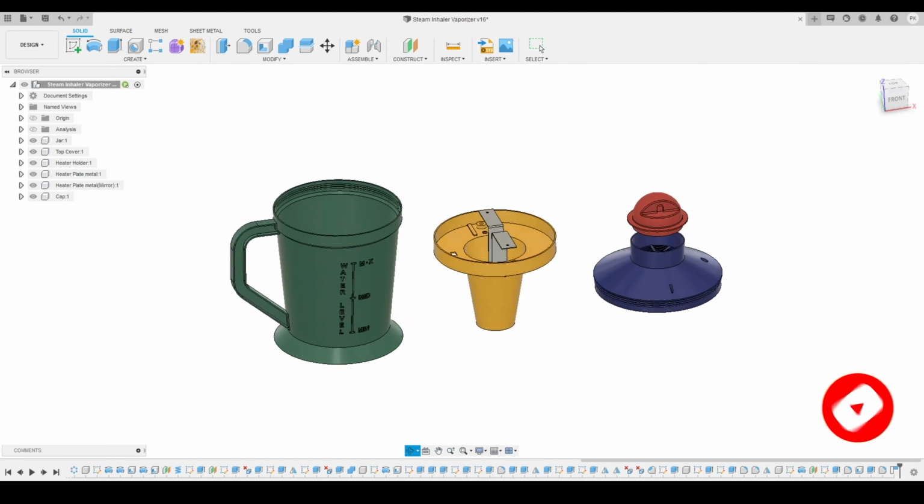Here you can see I just created this sketch, and now I will make this line and the origin coincident. So I had applied the constraint, then I will make this line a vertical line. So I had applied the constraint. What you have to do is select the entities that you want to specify in a certain position and then apply the constraint. So this is how it works.